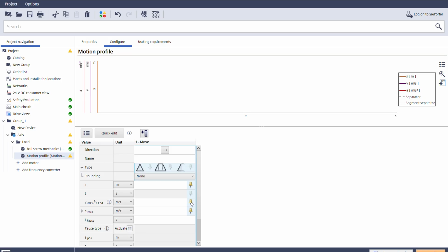So with these pins, what I usually like to do for today's is: how far are we moving this? What amount of time do we want this to take to move? And then what type of motion are we looking for? I'm going to go to the trapezoidal figure here, basically defining a constant acceleration to speed point and then constant deceleration to stop when we turn it off.